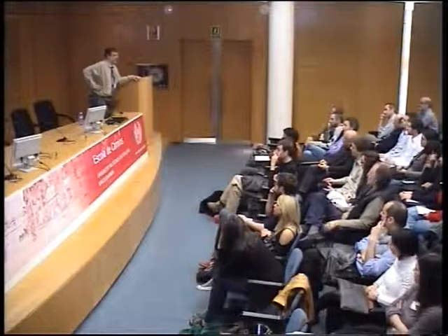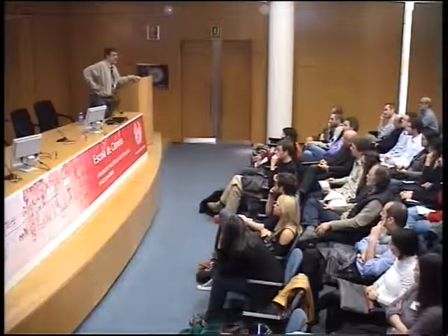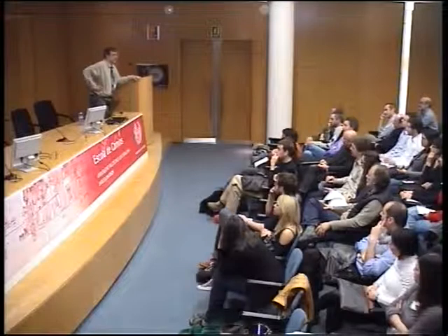The situation, of course, is quite different here in Spain, because in steeper environments, you can often maintain reservoirs for much longer times. Sluicing of sediment from reservoirs actually is a topic that involves turbidity currents, and since I like turbidity currents in the ocean and reservoirs, I know something about it. And the key feature here is that you can use sluicing to get rid of part of the fine end of your sediment load. The coarse end stays upstream in the delta, and the delta progrades down, and as far as I know, no one has ever found a mechanism to successfully sluice that material out. So it can be a partial solution.